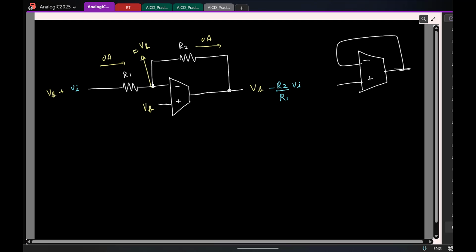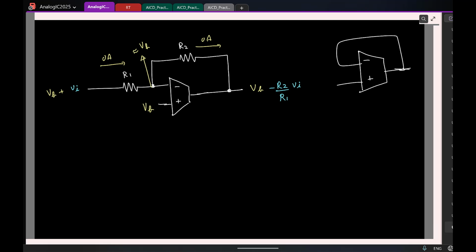Then the calculations will be different. So it is not practical to specify for a particular circuit because you never know what is the end application of the op amp. All you know is the customer will use it in negative feedback, but what kind of circuit is not under your control.